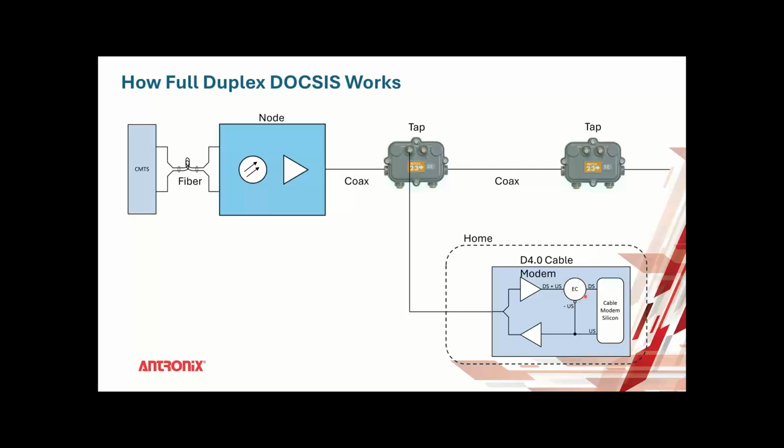So this feature within the cable modem is a technology that actually allows the echo, the return loss, the signal that's transmitted and reflected back, to be canceled. It's called an echo canceller. How does that work? If I'm a cable modem, I know the signal I'm transmitting upstream. If I know what I'm transmitting, I can create a negative of that, 180 degrees out of phase, and put that signal into one side of the echo canceller.